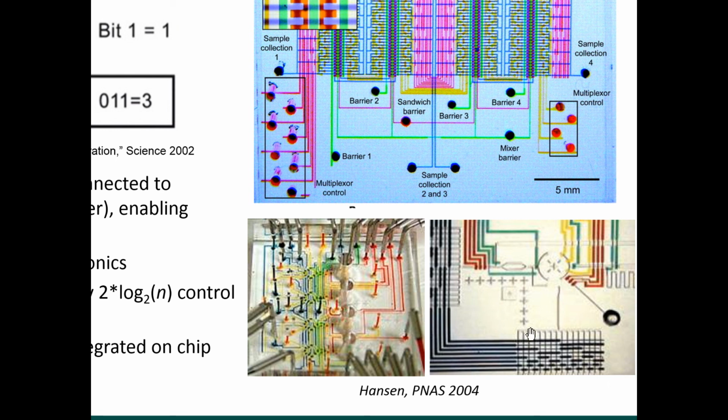Now, in this binary multiplexer, they've actually injected black liquid into the channels so that you can clearly see where the valves are. Otherwise, PDMS's transparency would be difficult to see. So these aren't fluid lines. They're actually the gas pneumatic control lines. So there should be only gas filled in the channel. So this is just an illustrative picture.